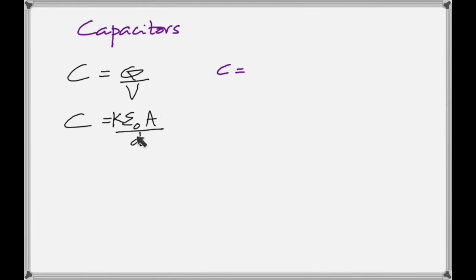That means get the plates as close together as possible, which is a dangerous situation because then there is a chance of sparking, and that's avoided by using a dielectric, right? So that's why we have a dielectric. Also look at the uses of the dielectric, please. That will be something conceptual there. And like I said, capacitance is in farad, coulomb per volt is farad.